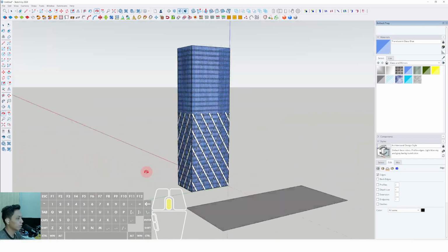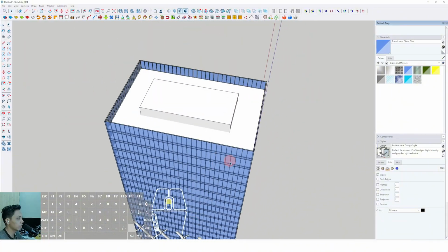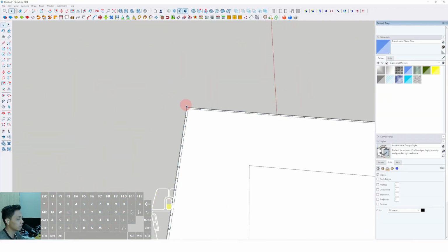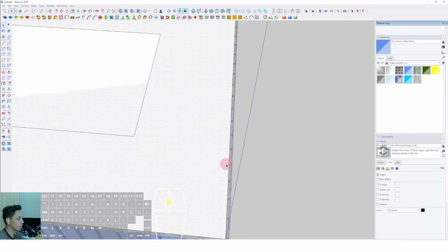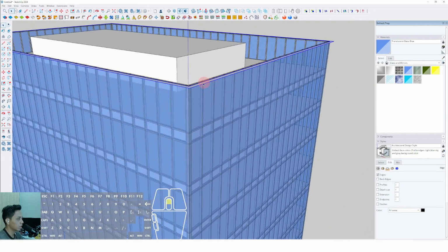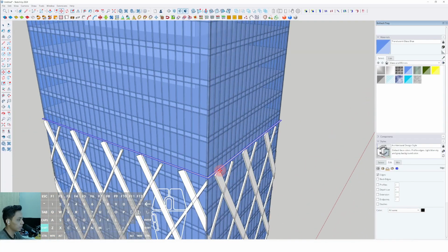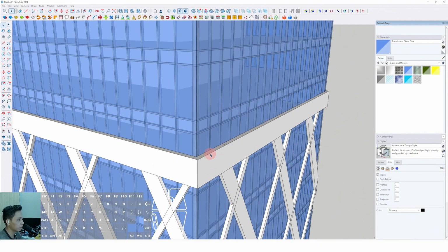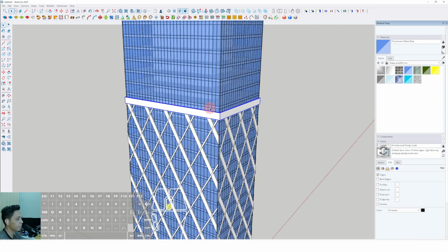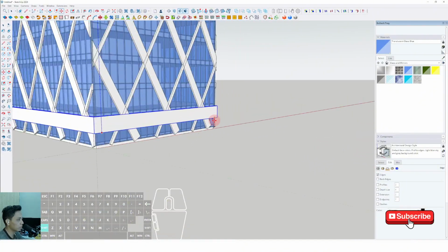Okay, now we can get the result, and we can also add the limit or boundaries to this edge. We can click from this corner to the another corner, then we can select offset to the outside and delete from this plane. Select this plane, select a move, place to the another position, triple click, we have to push it up, triple click, make group, and also we have to select a move, press Ctrl and place to the another position.